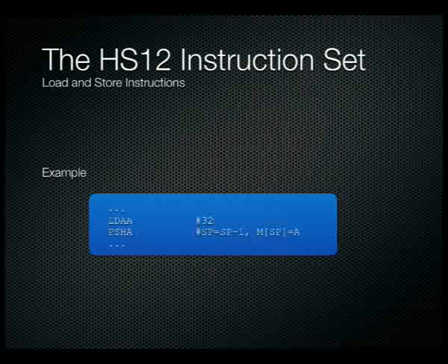So the M[SP] notation that I've mentioned here is a notation that I use throughout this lecture set. Basically it means that our memory, referred to in this case as M, is a continuous array of 8-bit values. So I use that notation to define that M[SP] is, of course, the memory location that SP refers to. It's like, I guess, the index value SP of an array called M that represents our entire memory map.